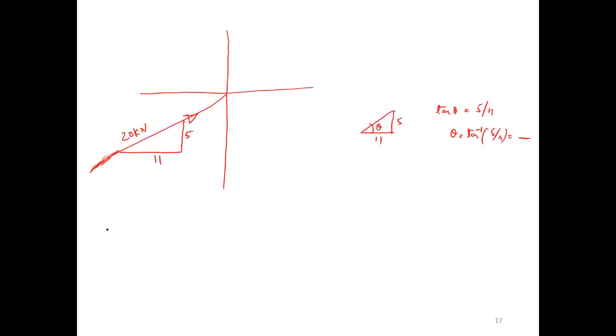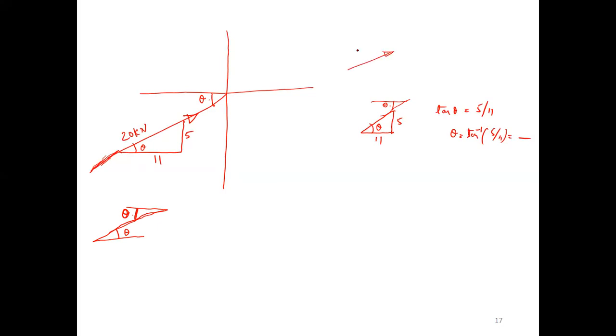Now you just observe this figure. This is theta now. By the opposite, alternate angles, this theta equals this theta, right? If you take this, it is the same theta value. Whatever theta you have computed here, you are shifting to here. Afterwards, you resolve. Now, how to resolve this? You get the horizontal and vertical components. This is towards, represent towards. The value I have given is 20. Therefore, this is 20 cos theta and this is 20 sin theta. Any doubts?